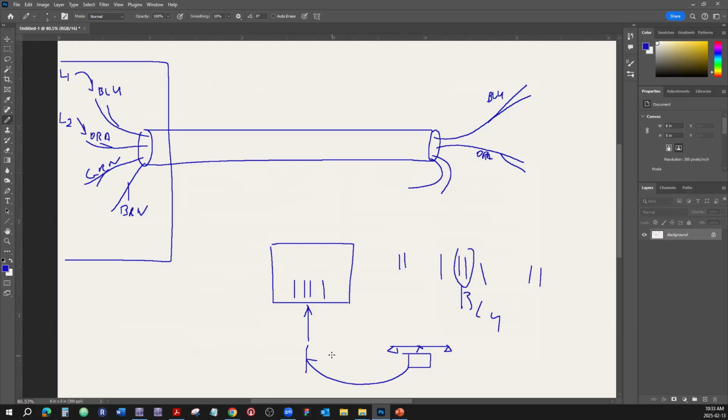The way things are made is that RJ45 is able to physically accept that RJ12 or 11 plug. You can actually plug in a telephone cord into a data jack. It physically will accept that. So, since the phone is looking for the signal in the two middle prongs, we're going to have to connect things to the two middle prongs.